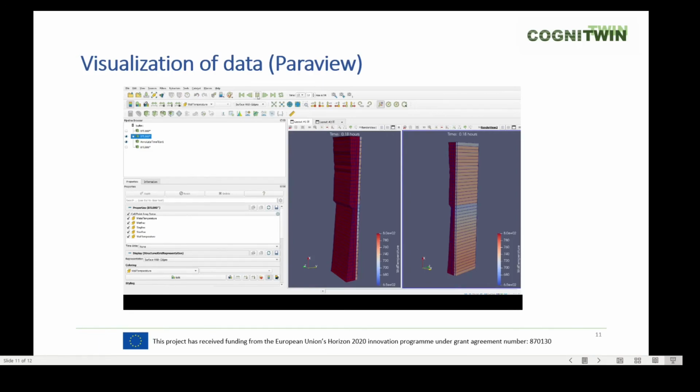the visualization, you see that the temperatures are actually initially somewhat lower at the point where the refractory is thin. This is because it is easier to drain out the energy during waiting time at these points where you have less stored energy. You also see that there is some gradient in the temperature.